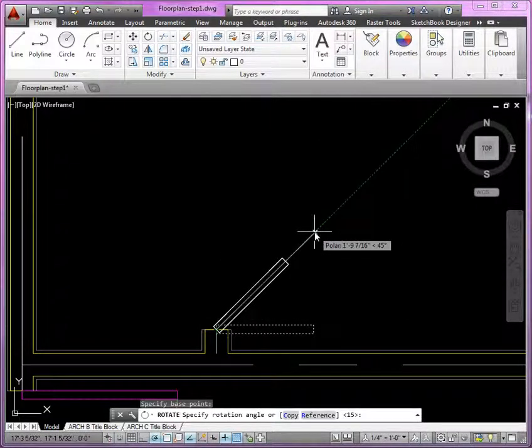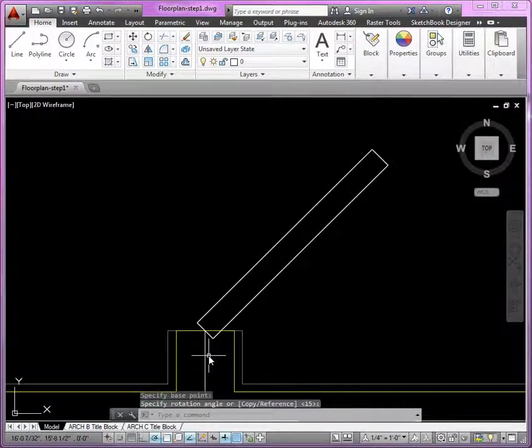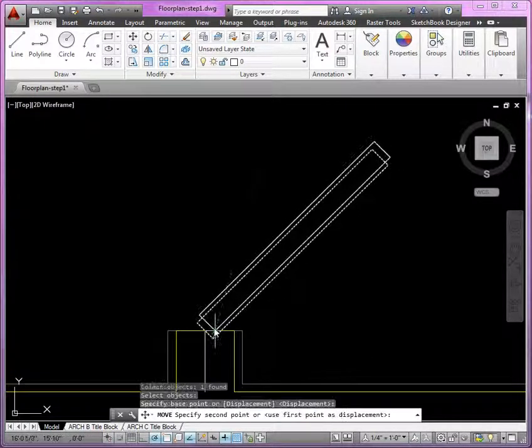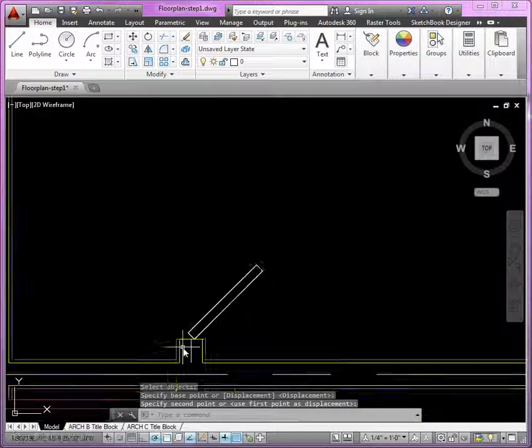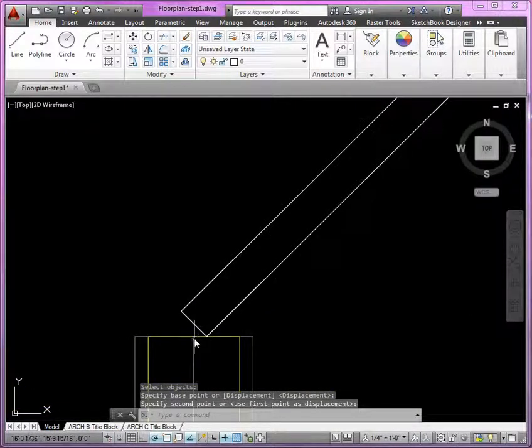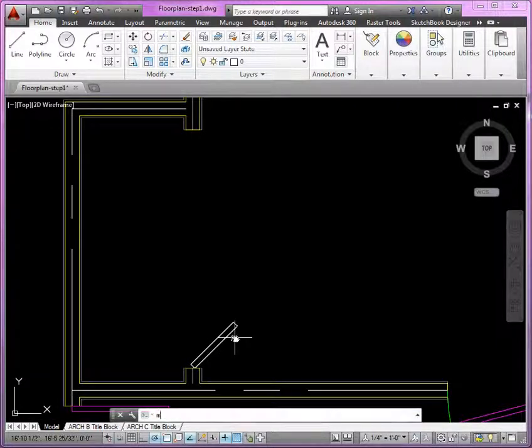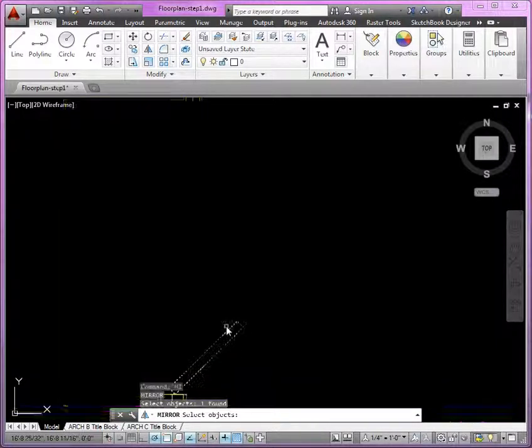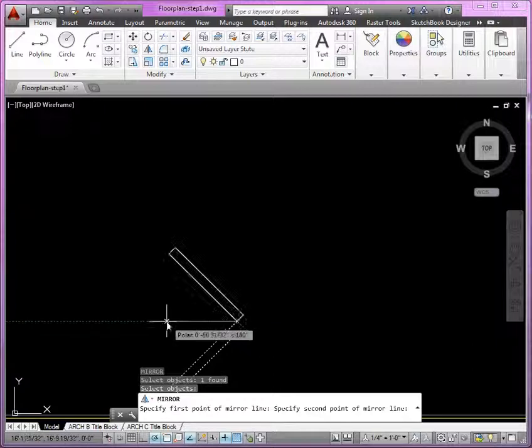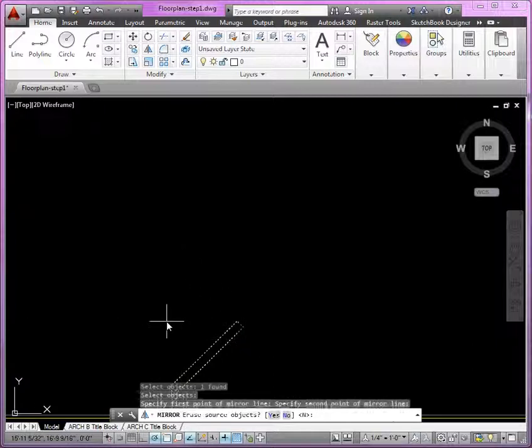And you can see we can reflect it like that. Let's move it out. There we go. So that middle still becomes the midpoint there, or the pivot point. And then here, I'll do mirror. Use just the corner there, and just use a horizontal mirror line.